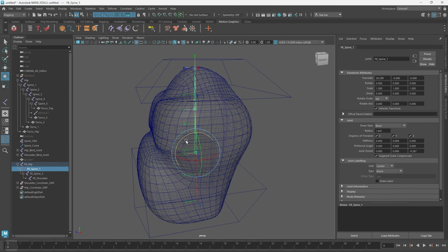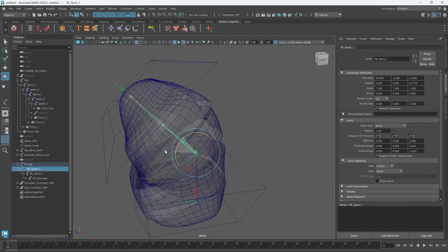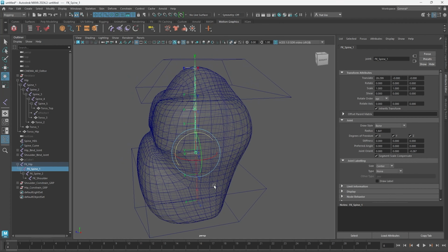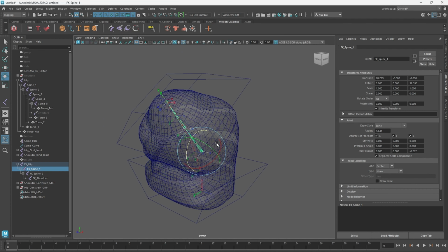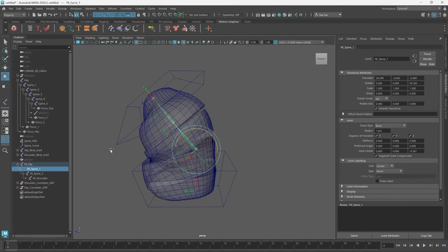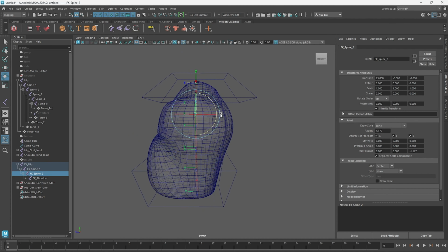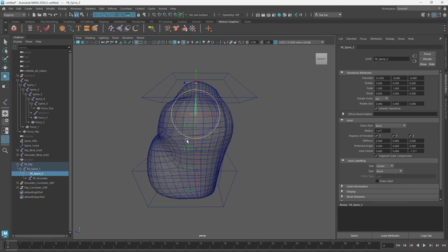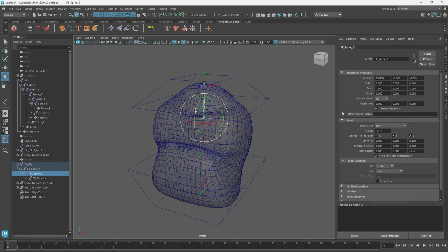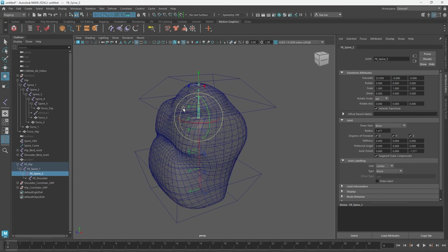And now you can see if I move this chain, it's going to move the controller that is my shoulder and also my hip too. So now all I have to do is to constrain these joints to controllers that control my middle portion of torso and then upper middle portion of torso. And I'll get more minute controls of this torso that way.